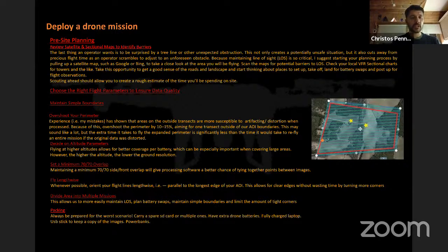For this reason, we can review satellite images and maps in order to identify any barriers or objects or anything that might be difficult, even small creeks, or to understand the terrain, etc. Because we also need to walk to a place that is close to the site that we are planning to scan.